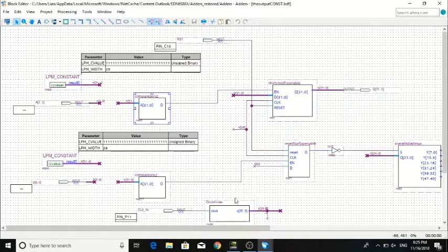This is the clock. When the first 28 bits of the address is 1, the compare 0 block ensures that the last 4 bits of the address are all zeros. The output from this block will then be 1, and this enables the 32-bit register to store the value of the 32-bit data input. The last 24 bits of data value of the data bus input is then shown on the 7-segment display. For simplicity reasons, we will be making our data input the same as our address data.